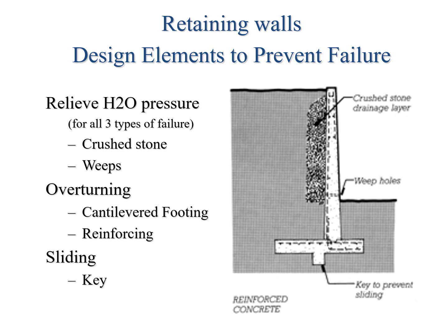Now the cantilevered footing is down below. As you see, the footing is offset, and there's a key placed in there. It's called a key to prevent the sliding. So that's another item. Those are all three of those items working together to prevent the three different situations we saw previously. The key keeps it in place. The cantilever helps to prevent failure as well.